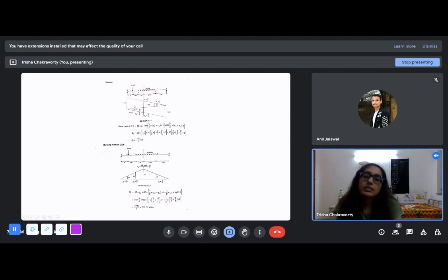Here, when there is a point load, you simply have to find the ordinate and multiply it with the magnitude of the point load. But when there is a uniformly distributed load, you have to find the area and multiply. So 60 into this, which is a parallelogram, so half into (yD plus yX) into 1, because this is 1 meter. We already know yX is 3 by 7 and yD will be 2 by 7, I mean minus, you have to take it with sign. So 60 into half into this into 1. And for this zone, the ordinates are positive, so 4 by 7 plus 2 by 7, into half into 2, because this length is 2. This is basically just a parallelogram.